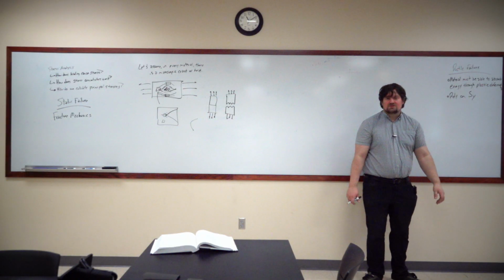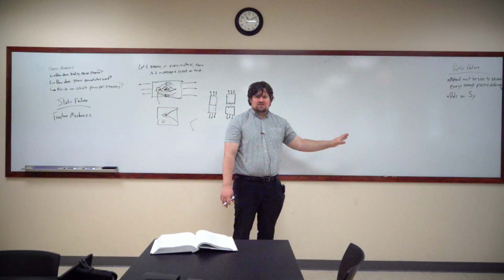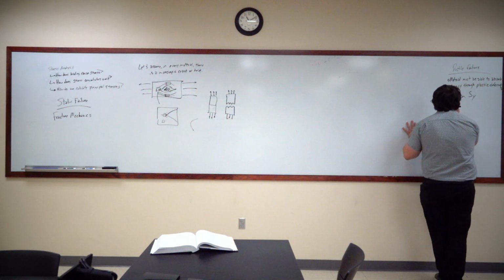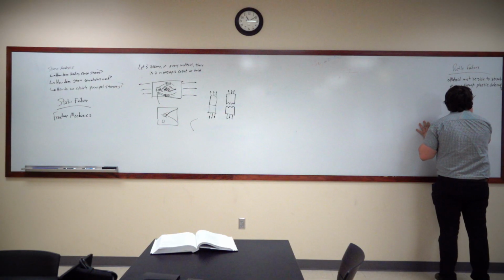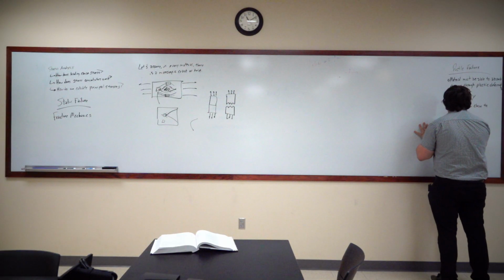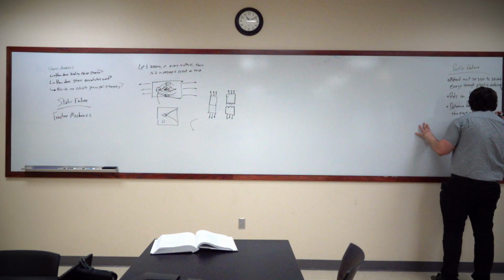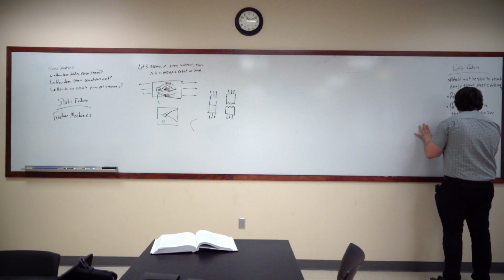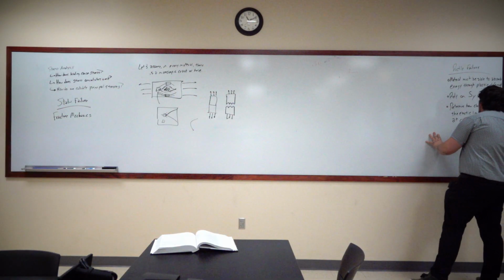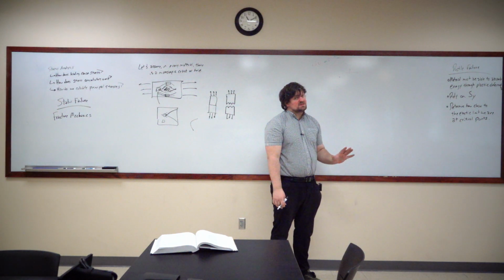That's going to be a differentiator for ductile failure. All of our ductile failure methods rely on the yield strength. They do not rely on ultimate strength. And in evaluating ductile failure, we're looking at how close to the elastic limit we are at critical points. And that's basically the whole evaluation.